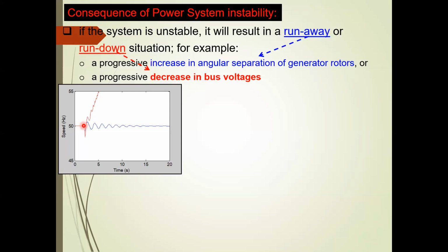The generator has inertia, whether you have a thermal power steam generator or a hydro generator, they will still be running. Suddenly the load is cut, through a switching operation for the load, but the generator cannot be stopped suddenly. The generator has inertia and it will continue to rotate. Because of that, the system frequency will increase here.